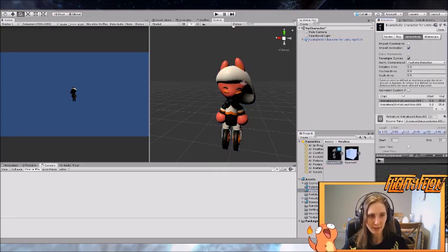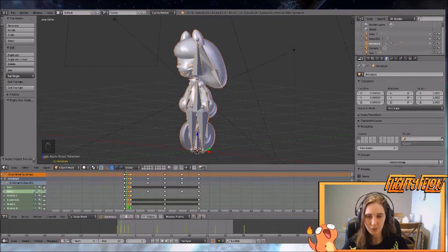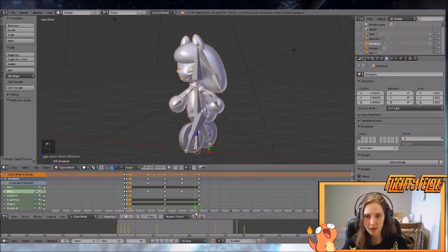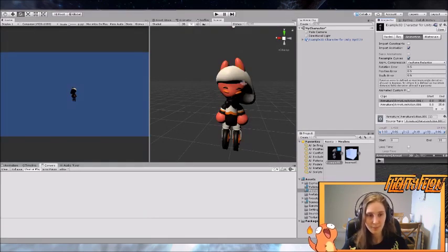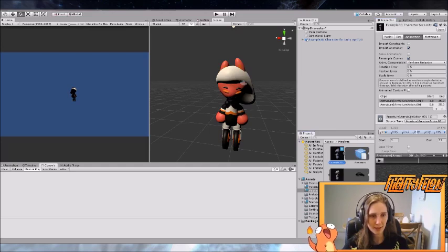And so let's go back to the meshes. And to the animation tab. So if you remember, the animation ran from frame 3 to frame 35. So you want from 3 to 35, and let's see how that looks. Nice. Okay, there we go. So you kind of open this guy up, and let's name this take to be walk.